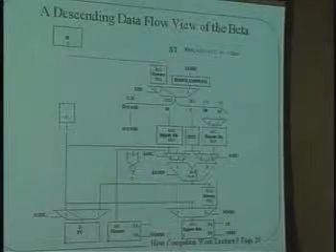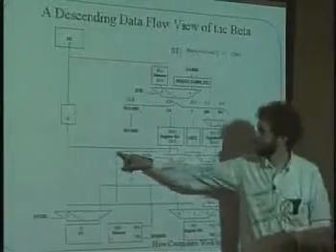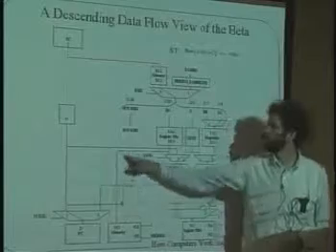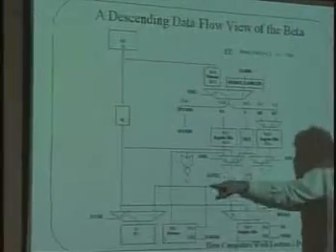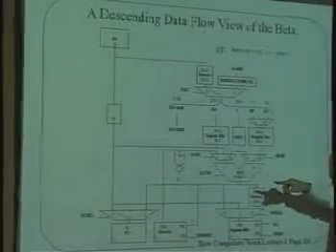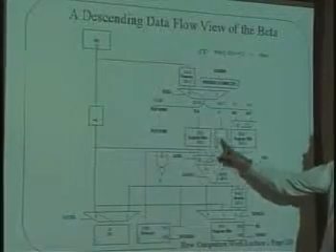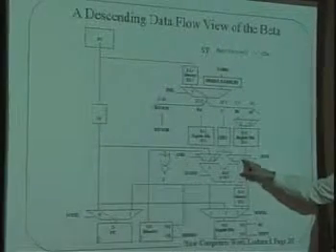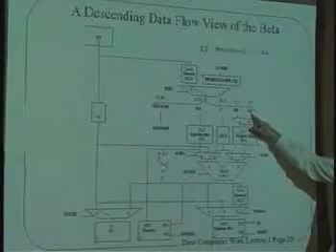Now, what data are we actually going to put in there? The contents of register A. That comes right over here and goes straight down into here. No computation at all is being done on the contents of register A. However, the address in the big slow memory that we're going to write the contents of register A to is going to come from the ALU. And what location are we going to write? We're going to write the constant C plus the register, the contents of RC.